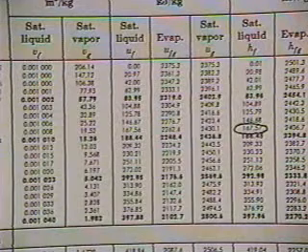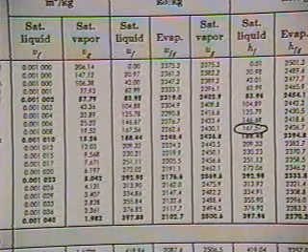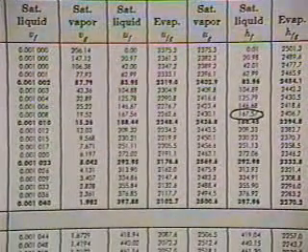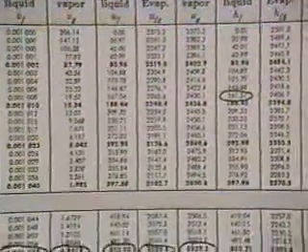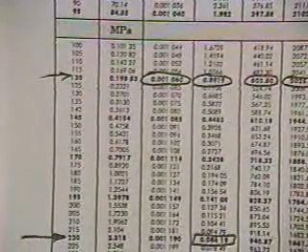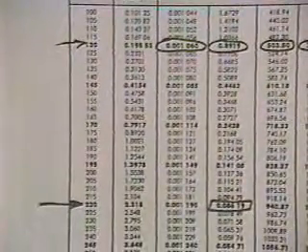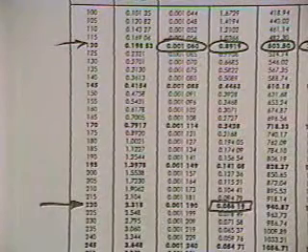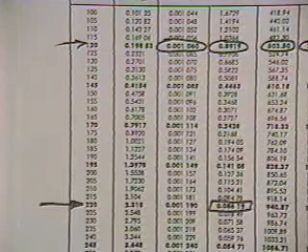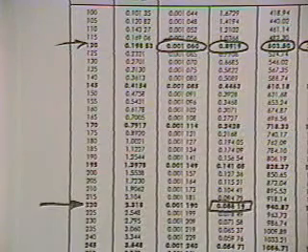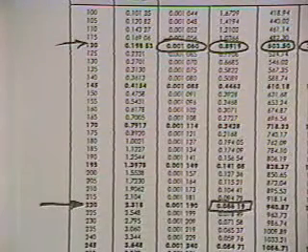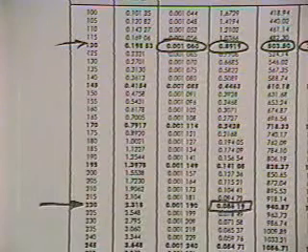Okay, we also can find state 2, and state 2 we know we've got saturated vapor at 1 megapascal. And so now let's go down to our tables till we come to a pressure of 1 megapascal. And if you notice on your tables, this is a temperature table, not a pressure table. Some of the thermodynamic tables will also provide temperature data as well as pressure data. But in our particular case here, this is set up so that it's in even increments of temperature.